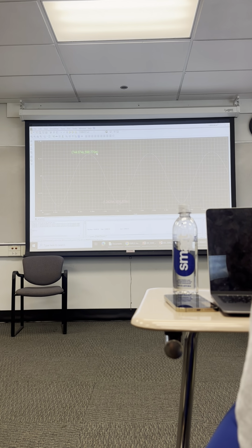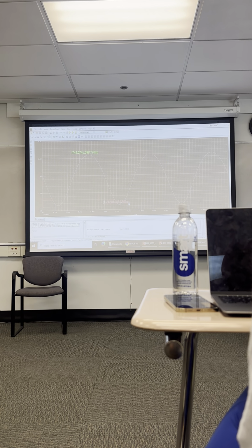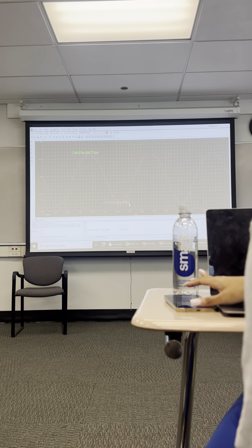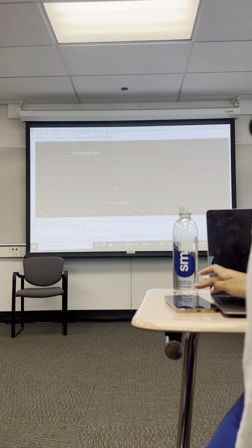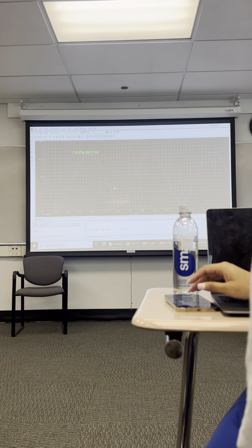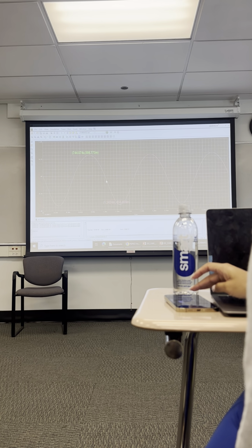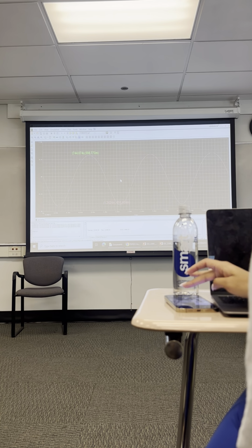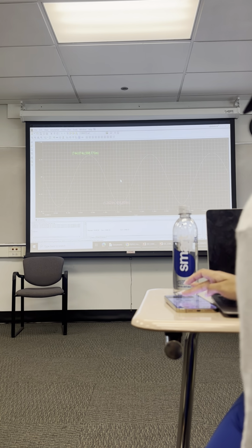Now these are in millivolts here, and the input is 0.02 volts, which is 20 millivolts. So what gain are you after? Are you getting 72,000 or 72? 72,000. That's what they got. They didn't convert it. How do you convert it? All right, we'll use another calculator. Calculate the gain.